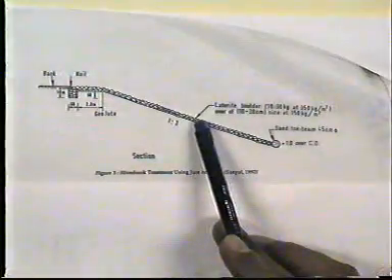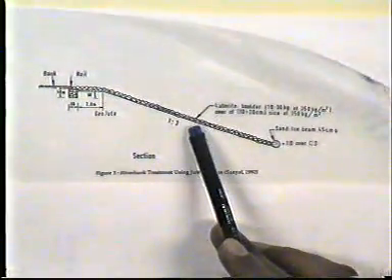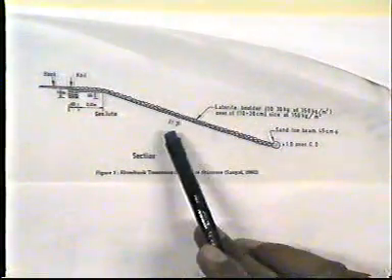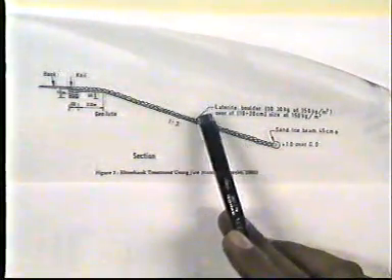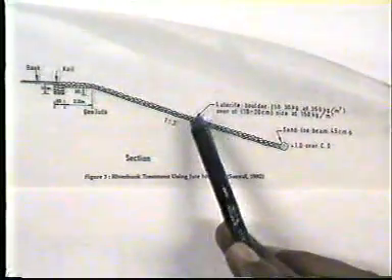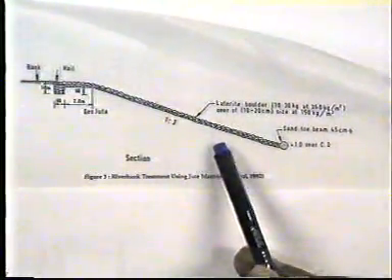And this is the river bank erosion protection. The jute was strong enough initially to perform the function of membrane action and separation, and to resist penetration of the wrap by puncture.